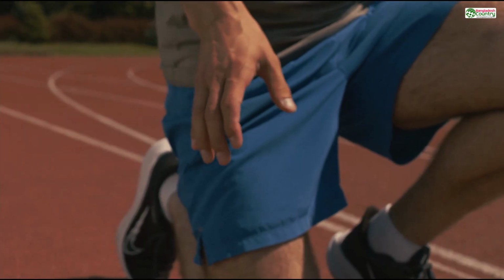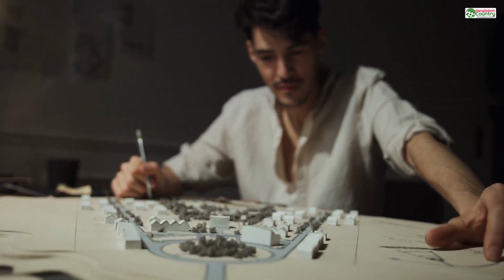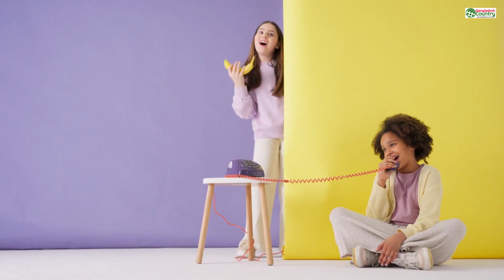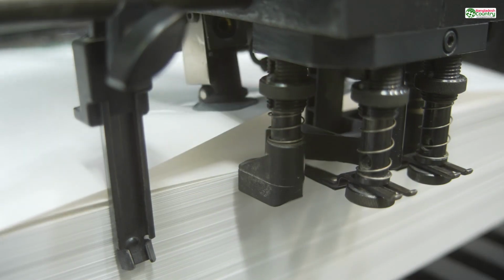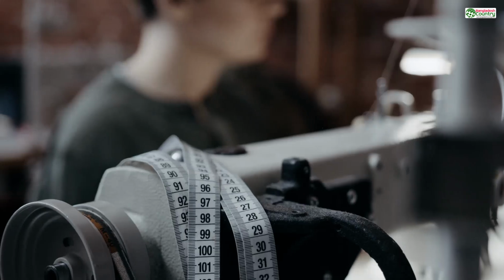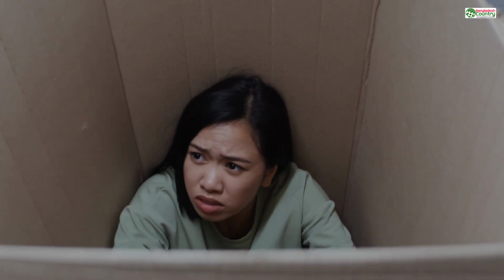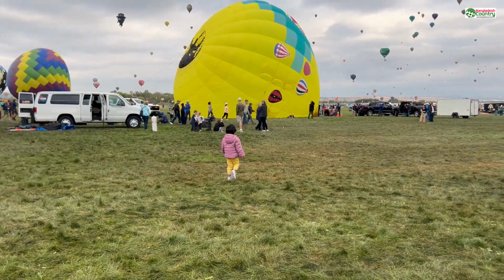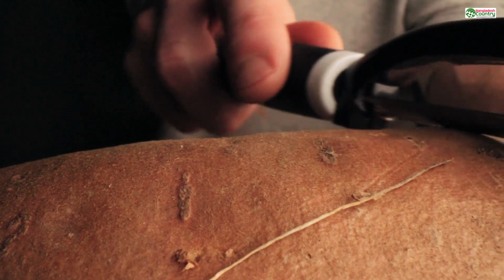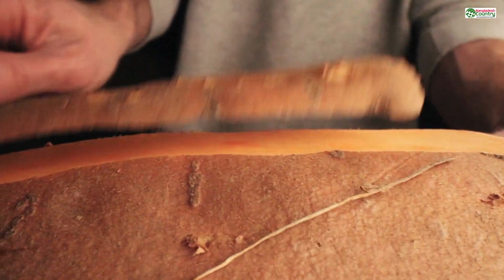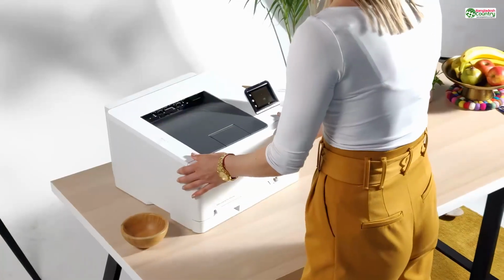So let's start with the single biggest reason for failure, the #1 assassin of 3D prints: creating a model that isn't watertight. Imagine your 3D model is a balloon. To print it, the slicing software, the computer program that tells the 3D printer what to do, needs to know with absolute certainty what is the inside of the balloon and what is the outside. If the balloon is perfectly sealed, it's easy. The air is inside, the world is outside. The slicer can then intelligently slice it into hundreds or thousands of layers and tell the printer exactly where to place the material.